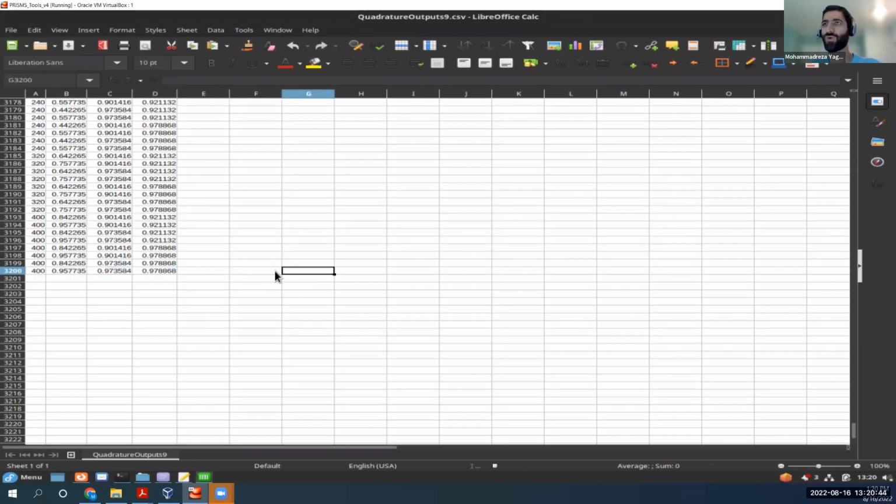And then let's say you want to average the stress within the grain with the grain ID of 400. Then you can easily write a MATLAB script and post-process this file and say, whatever grain ID is 400 on the first column, then you can average, let's say, sigma 11 over those quadrature points.